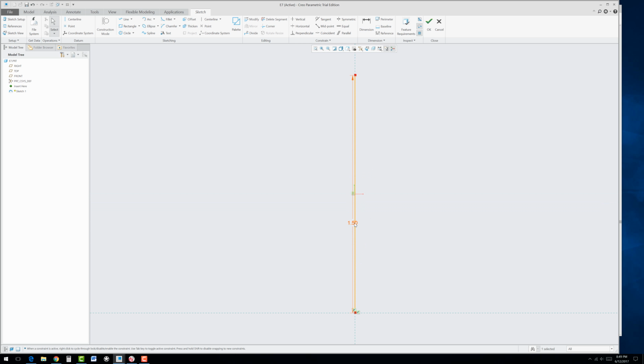Now to bend it, we're essentially going to project it onto what you might think of like a die almost. So select your right plane in your feature tree and go ahead and start a new sketch. Take the line tool and right at the origin there, click and drag out a short little line. You can see the solid line that goes along here. That's actually your sketch from earlier. Let's go ahead and right about there, click, drag it down at about a 45-ish degree angle, click, and then drag it clear across just like that. And now middle click a couple times.